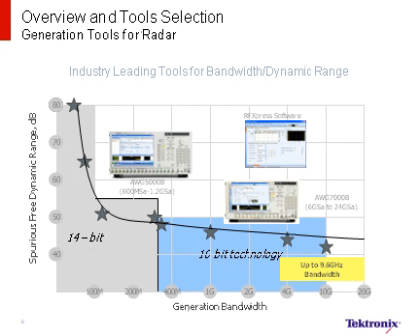In addition to measuring radar pulses, we can also generate pulses to test receivers or transmitter components. The Tektronix AWG5000 and 7000B arbitrary waveform generators provide industry-leading performance that can make pulses up to 9.6 gigahertz in bandwidth, sampled at 24 gigasamples a second. Single-channel, multi-channel, and digital interfaces are available for optimum flexibility in testing the different access points available in today's modern radars. Our RFXpress software with Option RDR radar offers the most advanced signal generation software available for radar transmitter emulation and receiver testing.